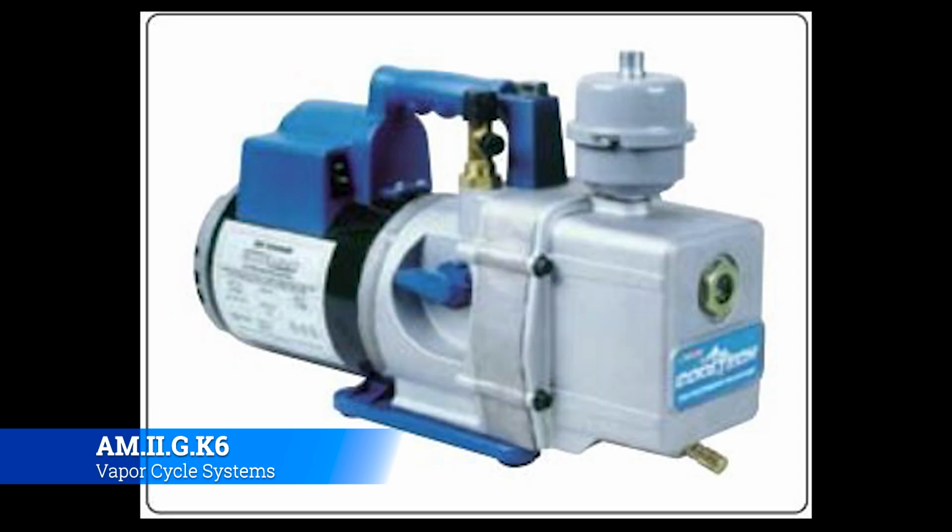Okay, this is a vacuum pump. You should be really familiar with the idea of a vacuum pump, at least, because we mess with them in composites. There's not really just a whole lot different between the two. Essentially, what you're going to use a vacuum pump for is you're going to hook it up to the system, and you're going to pull a vacuum on that entire system. You're going to pull every bit of air, old refrigerant, and everything out of that system, so that way you have this intense vacuum happening, so that when you introduce the refrigerant into it, it goes throughout the whole system in the blink of an eye.